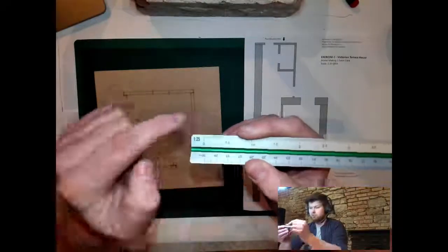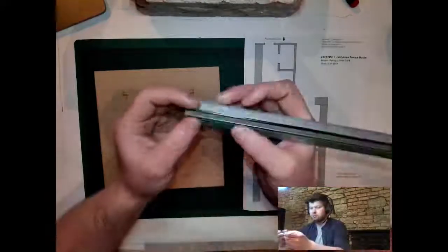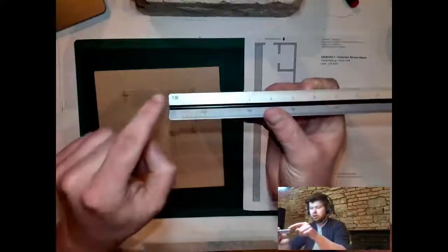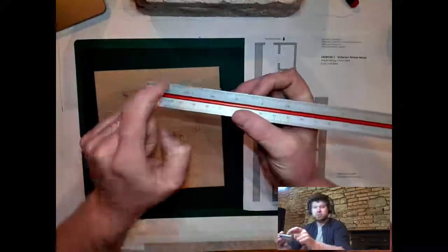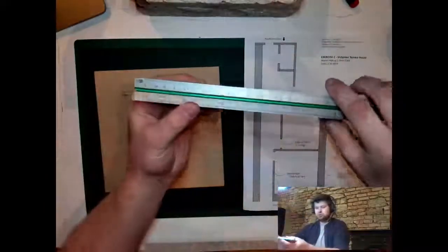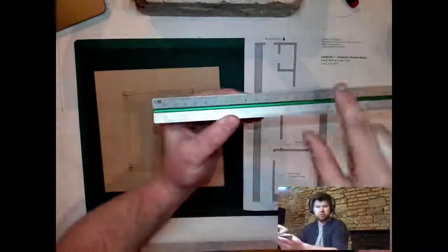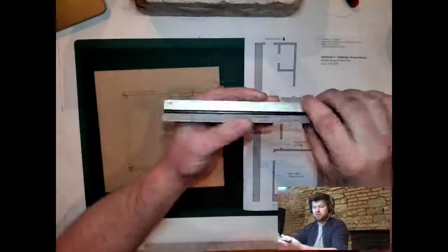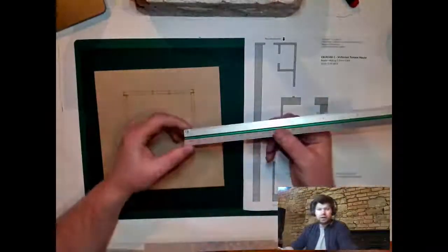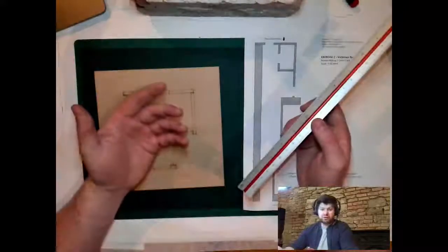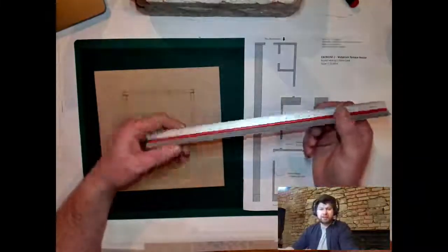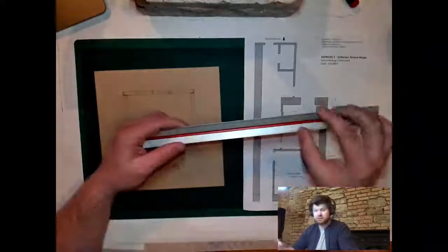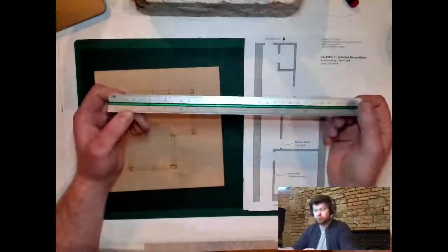So this is 1:25, so everything along here is 1:25. If I move it to the next corner, 1:50, so all of this scale is 1:50. And 1:20. And if I turn the ruler around, we also have scales on the other side, so 1:100, 1:75, etc. So, for example, if I wanted to draw something at 1:100, it means that in real life, it's divided by 100, and that measurement is automatically shown on this ruler without doing the calculation.